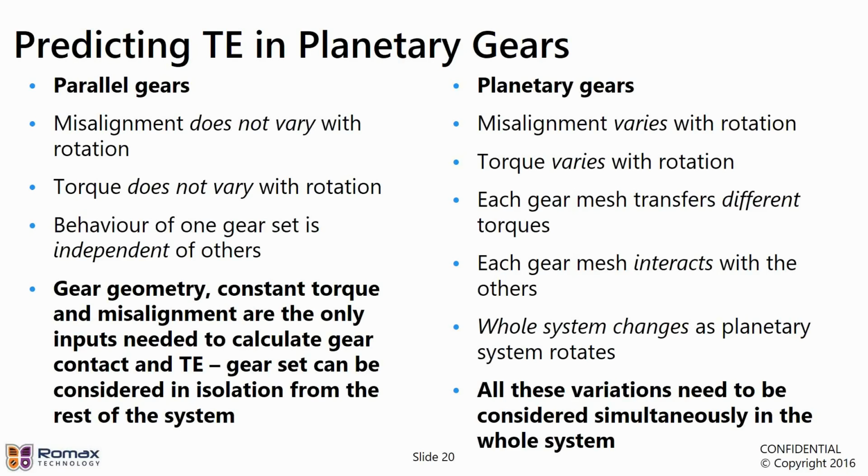It's much more complicated. We have misalignment that varies with rotation. We have torque that varies with rotation. We have unequal load sharing. Each gear mesh transfers different torques. And also, we have all these very closely coupled gear meshes, and each of those interact with each other.